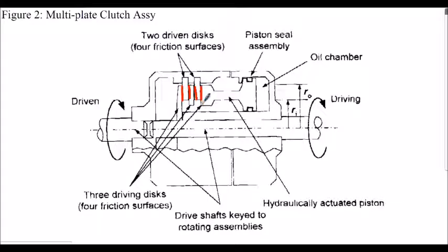And of course, the more pairs of contact surfaces you have, the more torque you can generate. And we'll be looking at this later on. It doesn't really affect our calculations greatly having 3 or 4 or 5 pairs. We just really factor up the torque from one pair of contact surfaces. But as with belt drives, where we have multiple belts, we work out the power generated by one belt drive and then factor it by however many belt drives we have. And the same really applies to friction pairs of surfaces. But nevertheless, we need to be aware of the contact surfaces.